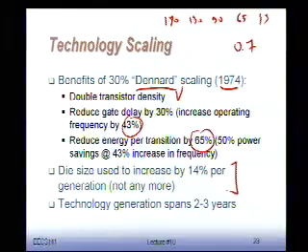And that's a good reason why, right? Suppose I keep on growing my microprocessor size, or my mobile processor size. At some point in time, the chip becomes bigger than your cell phone. That would not be a good idea either. So you're constrained by size factors. And cost factors, remember we talked also about the cost of yield, that if you make chips bigger and bigger, the yield might go down as well, cost can go up, and so on and so forth. But for a long time, 14%.